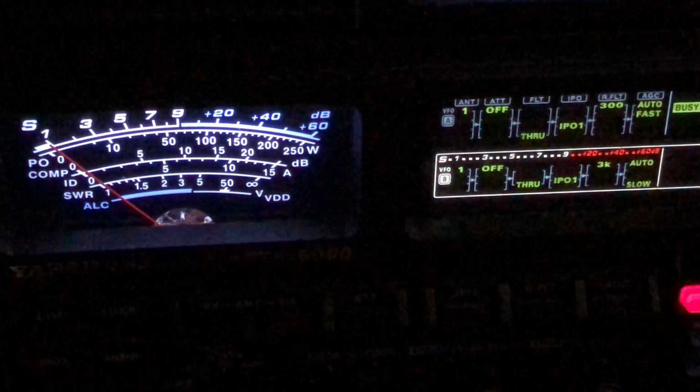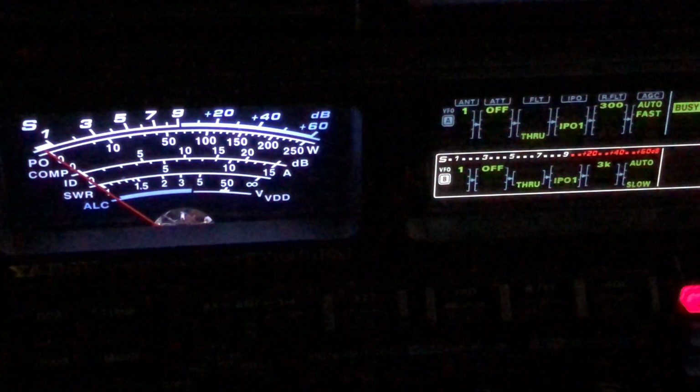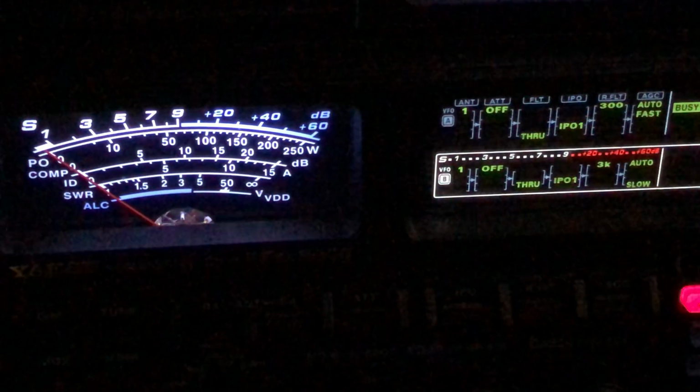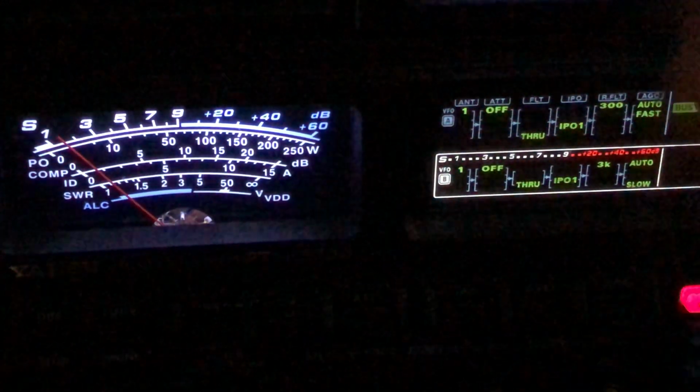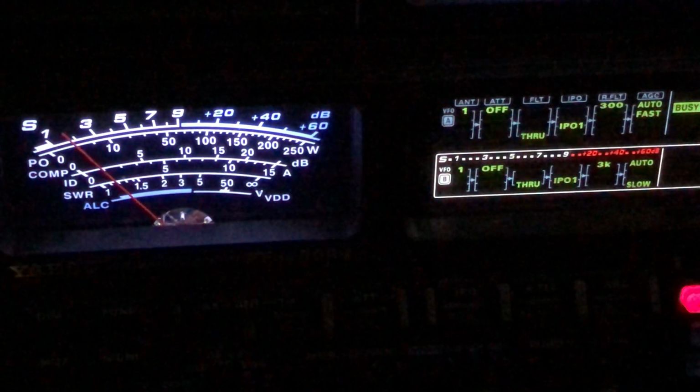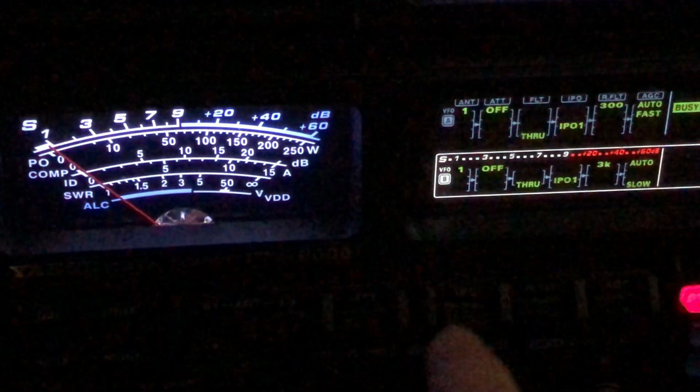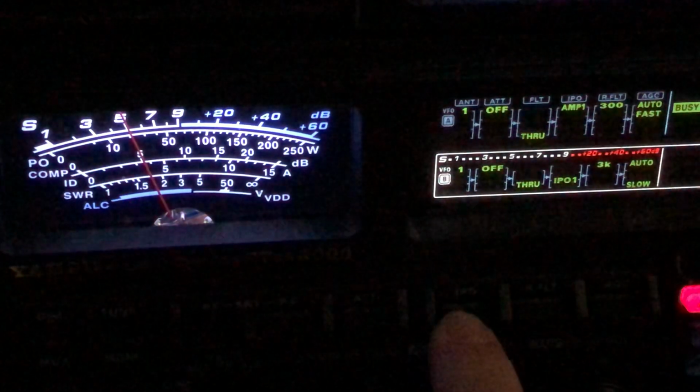I'm going to go to IPO, which is essentially on our Yagi radio. It means I'm turning off my RF preamplifier. I'm disabling the first stage of amplification in this receiver. Why? On these lower bands, I really don't need all that sensitivity. Now look what that did to the S meter. So I'm going to go back to default.